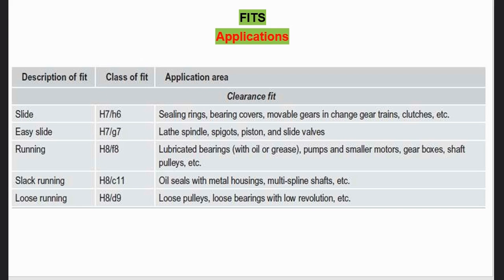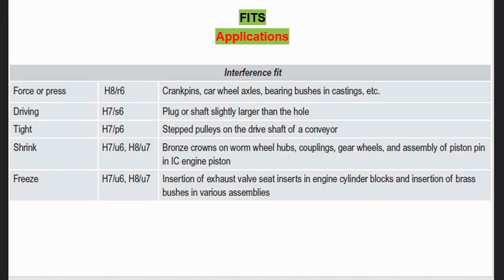Similarly, this particular slide is talking about interference fit. Here you can see I am representing a hole by using IT grade 8, or 7 in some of the examples, but the fundamental deviation here is H. That is called the hole basis system. What is hole basis system and what is shaft basis system, we will cover later on in the same lecture.